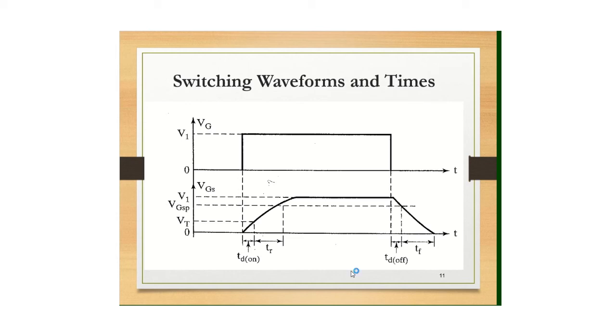So if we have to understand the switching waveform, we actually look into the characteristics. That is, we look at the turn on time and turn off time, right? So if you recall again, turn on time is the sum of delay and rise time, right?